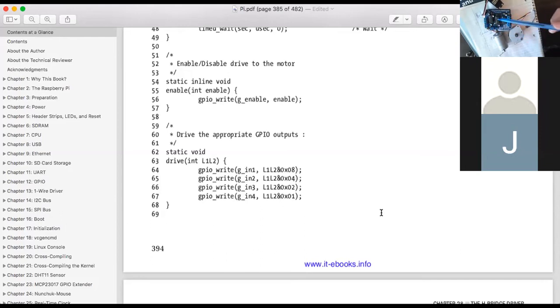So that implies this drive can drive not only one bipolar stepper motor, but can drive another stepper motor. So it can actually control 2 stepper motors, or alternatively, 1 stepper motor and 2 DC motors. I'm connecting this DC motor, so it can drive 2 DC motors, or 2 DC motors plus another 2 DC motors, for a total of 4 DC motors.